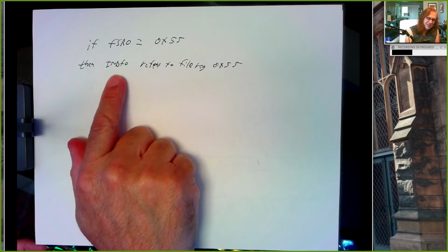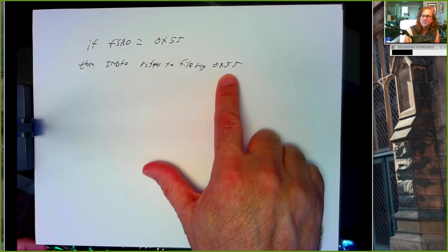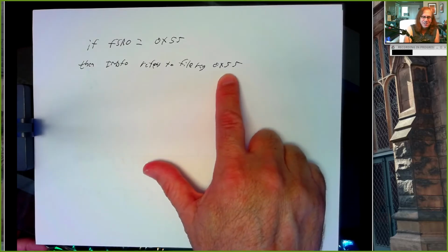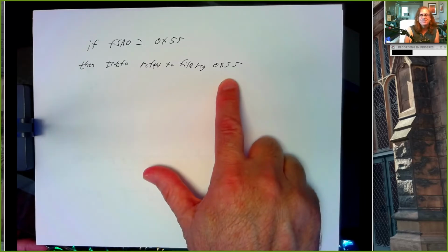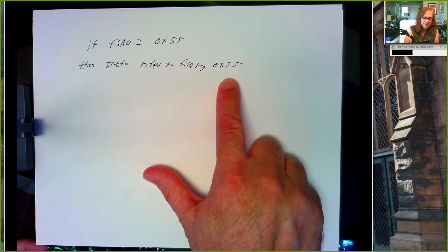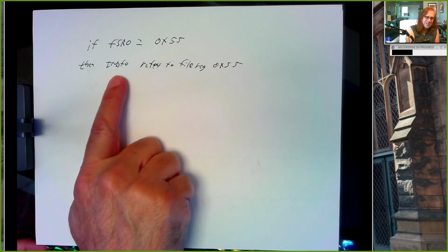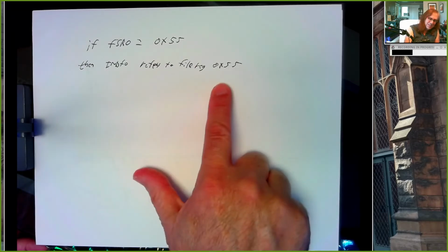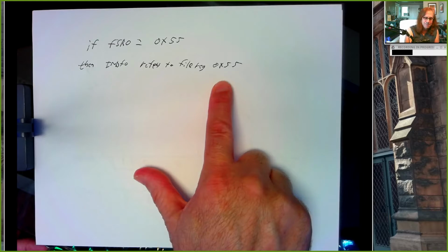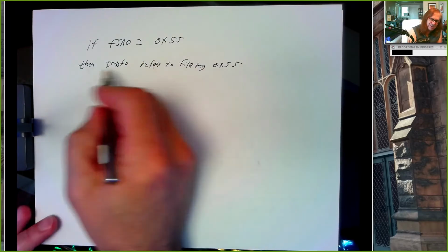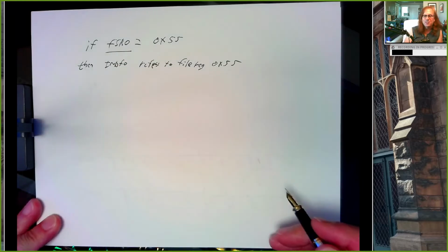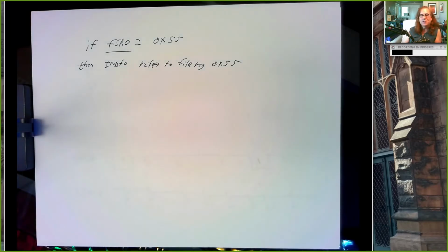If we clear INDF0, we will clear file register 55. If we test INDF0, we will test the contents of file register 55. If we increment INDF0, we increment the contents of file register 55. And none of these things affect FSR0. FSR0 is a separate register. It's actually a pair of registers, FSR0L and FSR0H.